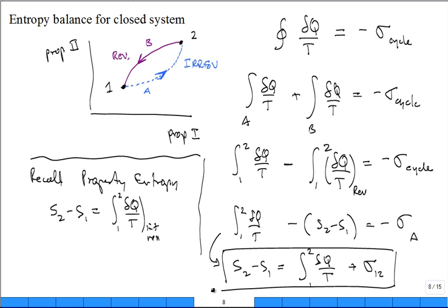Is an entropy balance statement. We derived it from Clausius's inequality using the definition of entropy for a closed system. It's an entropy balance statement for a closed system. We can interpret this part of the entropy balance statement as the change in entropy. It went up or down. How? Heat transfer. Heat transfer can bring in entropy or can remove entropy. If this Q is positive, then it's bringing in entropy. That means heat transfer in, entropy transfer with the heat in.